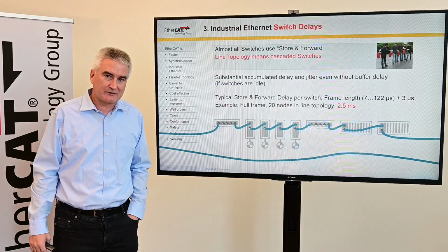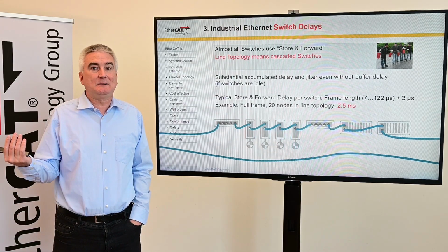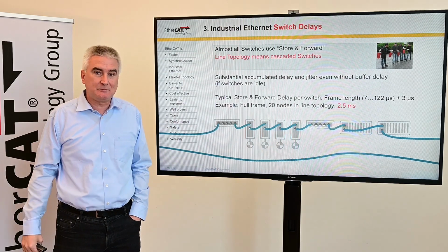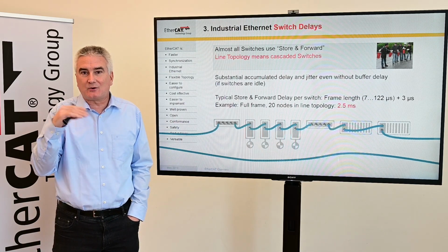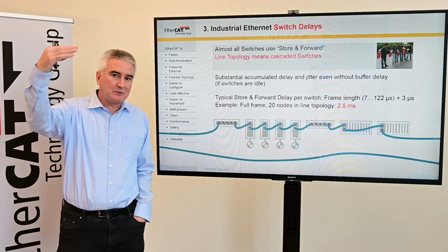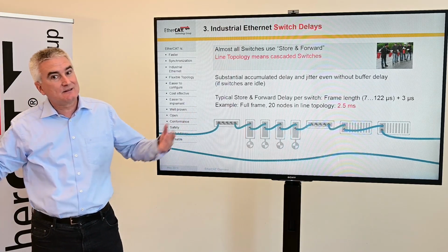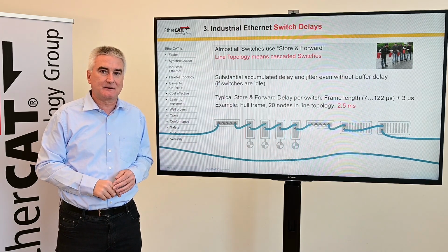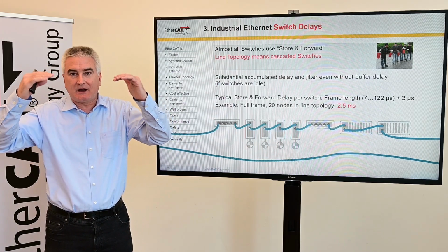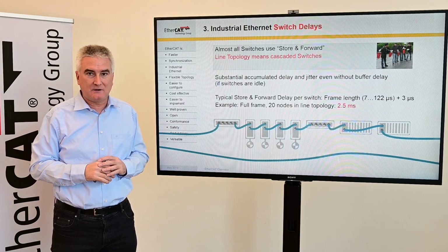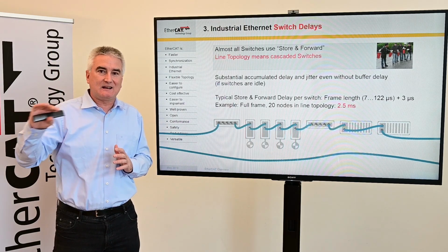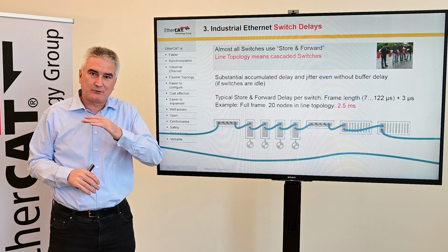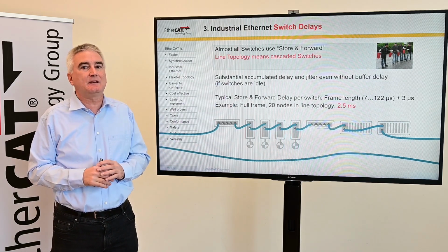Let's face it, IP, the Internet Protocol, typically is the threshold where the IT guys get nervous. Why? Because all the malware travels on top of IP. There's no Trojan or virus in the Ethernet frame. It's always on top of IP. Why? Because they need IP to get past the next router. They need IP for traveling. With EtherCAT, we're not based on IP. We're directly in the Ethernet frame. So we're avoiding the clash with the IT department. We're, so to speak, flying underneath their radar.